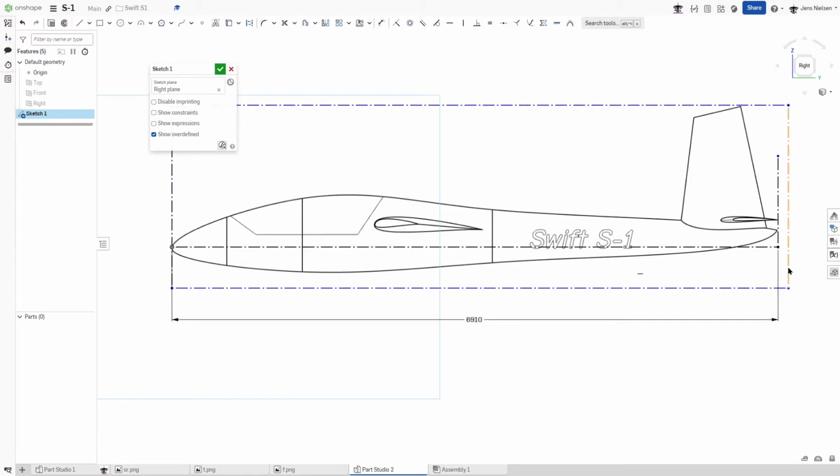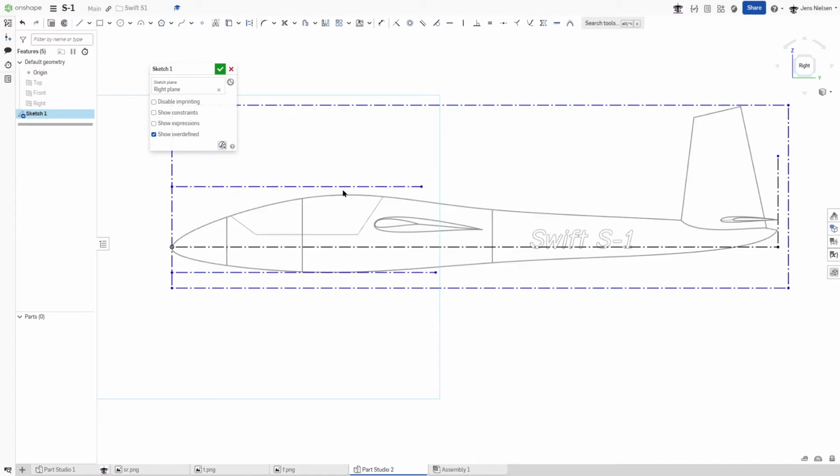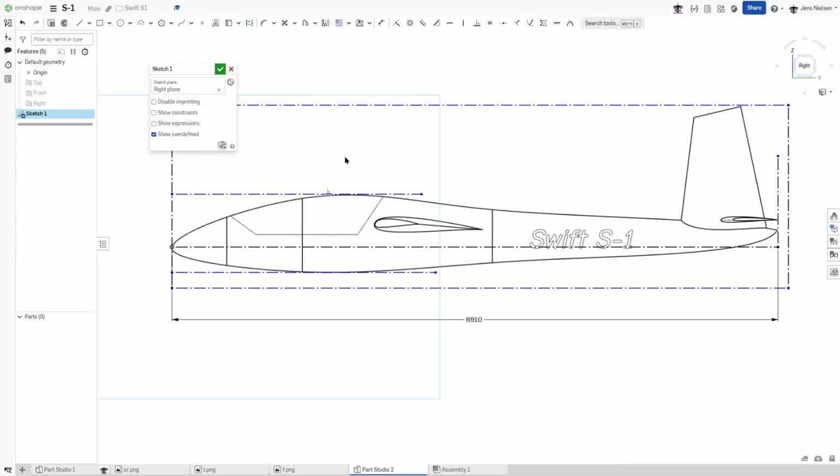All right, like this. With a Shift J, I can fix that line there. And I will draw one more construction line here, and one down here. And this is to find the deepest and most upward point of that fuselage. That'll help me to orient that front sketch. All right, that's it.